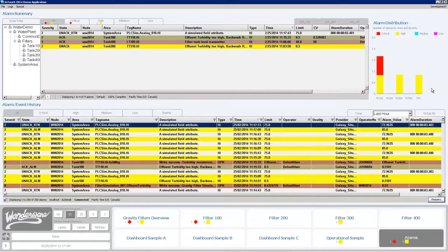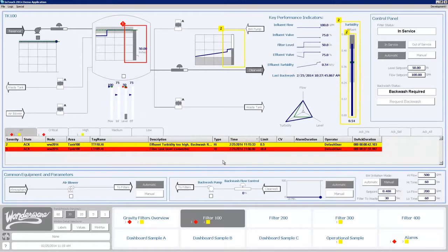These techniques of both using alarm borders and leveraging alarm aggregation should make it much simpler to handle large volumes of alarms. Alarm banners have been an ineffective way of handling a large number of alarms. You can see here that once I get to four or five alarms, I'm not going to be able to see what's happening in the alarm banner.